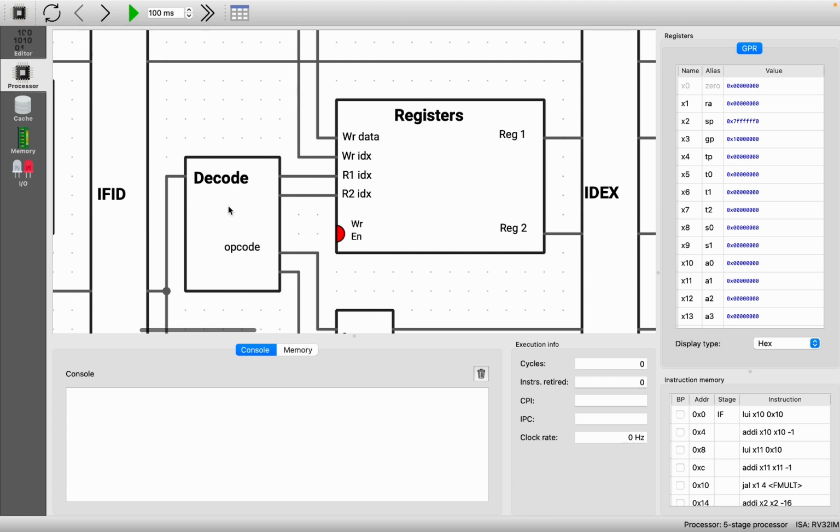And so this is why in RISC you do things like have fixed width instructions and not have post-increment loads and stuff like that. The more logic that you have to do in this decoder here, that doesn't add value, and you could use that hardware for something else.